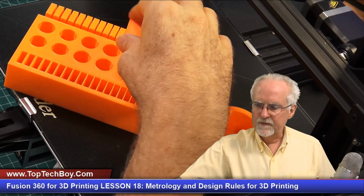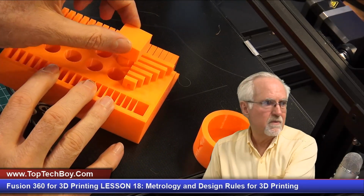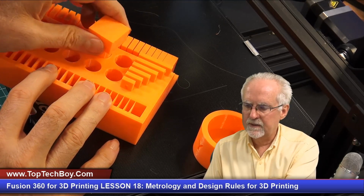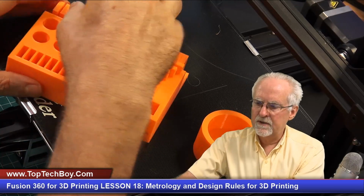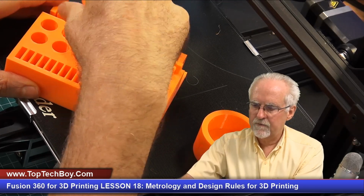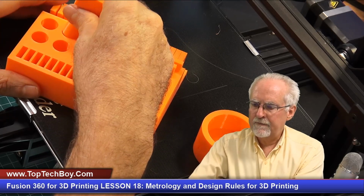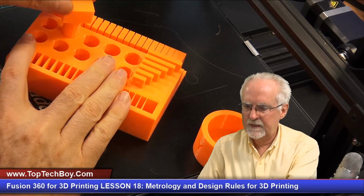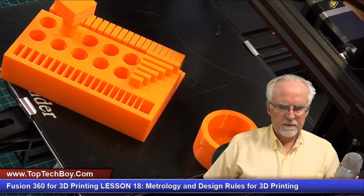So if I come up to 15.5, it certainly fits in, but it is way looser than I would want. A 15 and a 15.4 is a little bit more snug. A 15.3, it's still very, very free to move around. Okay, not hanging. This one would be a 15 peg and a 15.2. And I think I better check that design and make sure I'm remembering that right.